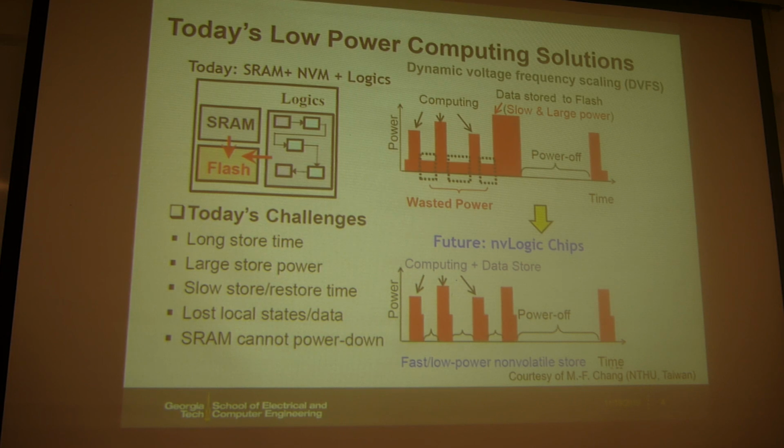When you are using the apps, then probably it's running at the maximum speed or even burst mode. But if you are doing nothing, then the clock frequency is only hundreds of megahertz. So this is just to try to save the power. But you cannot really power down the chip, right? Because this is like your standby period. You cannot power down your VDD